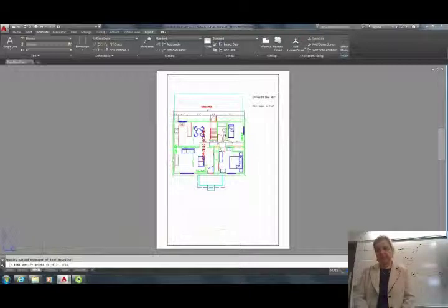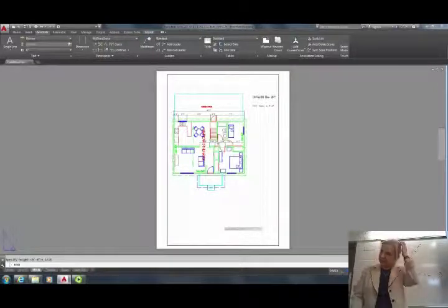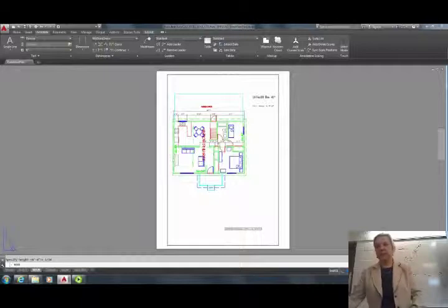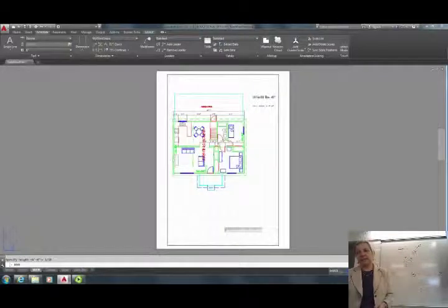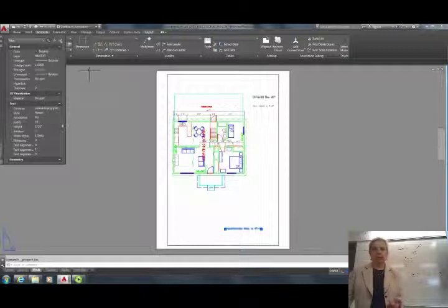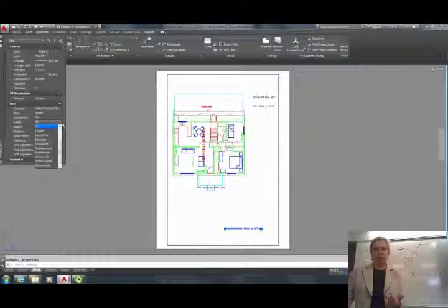Okay? And then I type something. Wall is 8 feet dash 0 inches, and the text comes up. My justification is fit, so I could probably change the property, and you shouldn't be using the fit setting. So to work with the notes, you should actually have top, is it top bottom?